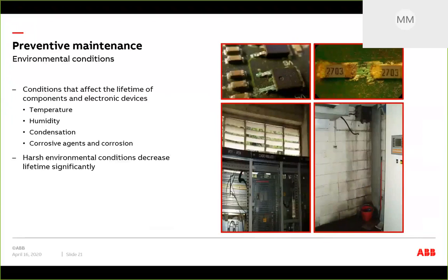So we're moving large volumes of air to keep those inverters cool. And if the room has a lot of humidity, a lot of buildup, or doesn't have a good pressurized, pure air room, things start to corrode like that. It's going to find the weakest parts on the circuit boards. Our boards are coated, but they're coated to withstand an environment of G2 or so. G4 would be the worst,